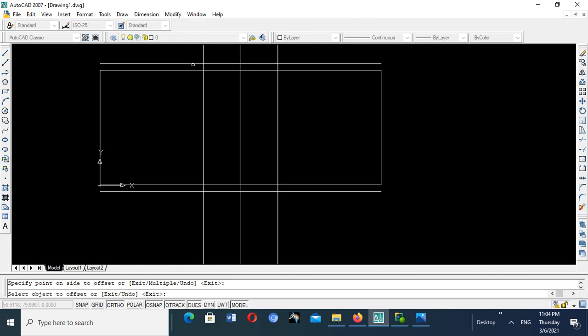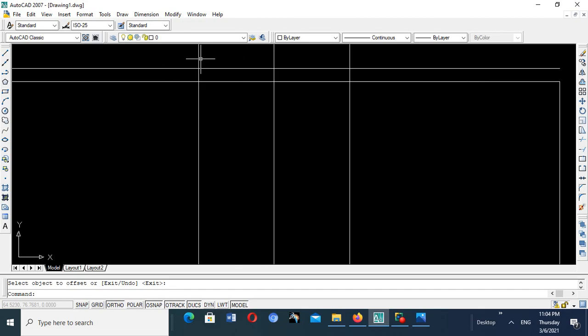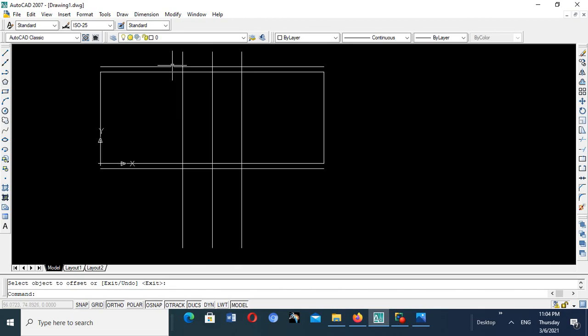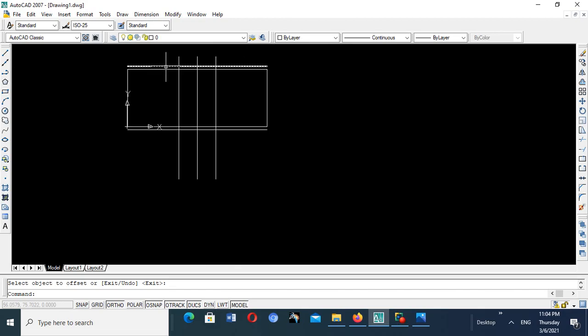So you go to your keyboard, you type TR, you check here, type TR for trim. Then you go to the key enter, you click it twice, enter. That's the short for what? For multi-trimming.